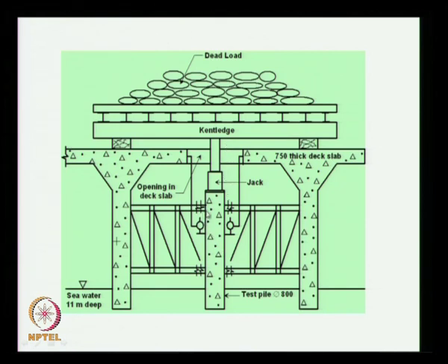And this frame is attached to this, and you can measure the, I am sorry, this frame is not attached to this, this is connected only to these two piles. You have 2 dial gauges marked here to the test pile, then this is connected to the rigid base, that is the slab permanent benchmark through which you can measure the settlement.